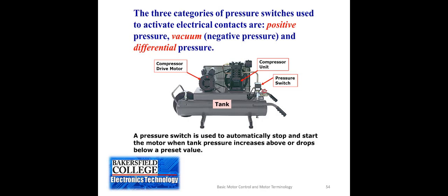It could stall the compressor and the motor will no longer spin, and then that overloads and overheats the motor. And if we didn't have a motor starter in that circuit, then the motor would just sit there and eventually start burning. So this pressure switch is very important, not only for safety reasons, but for the ability to operate this automatically.